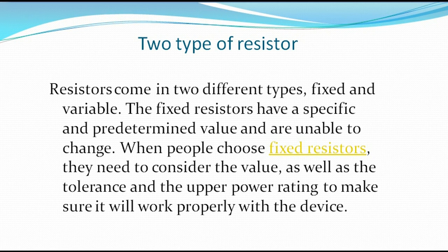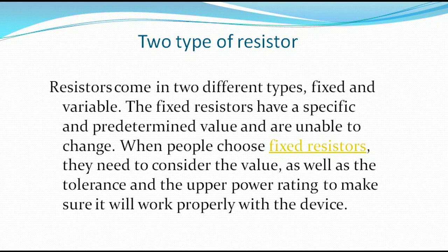If you are a technician building any circuit, or you want to buy a fixed resistor, consider the value, the tolerance, and the upper power rating to make sure it will work properly with what you are about to do.